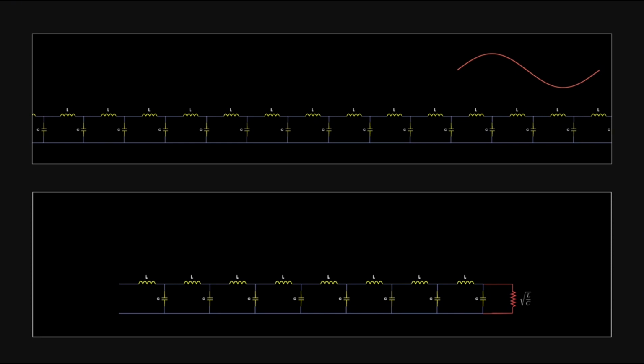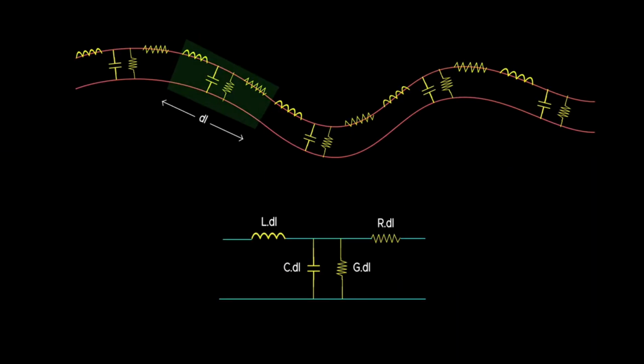So far so good, but how does the injected signal itself propagate through the line? To answer that question, let's analyze one section from the line. Even at very high frequencies, the signal wavelength would be very large compared to the section dimensions. Hence, the lumped element model is valid, and Kirchhoff's laws can be applied at each section.